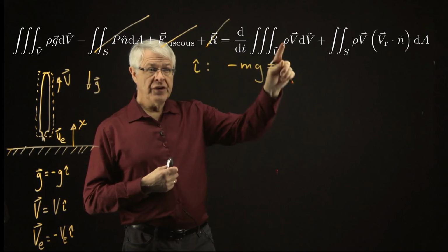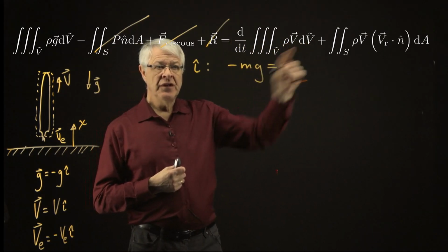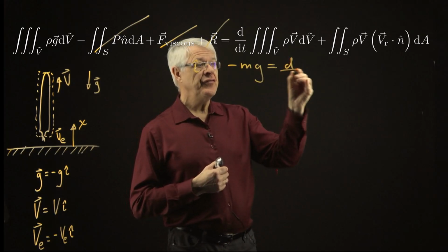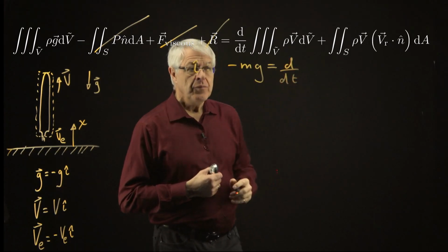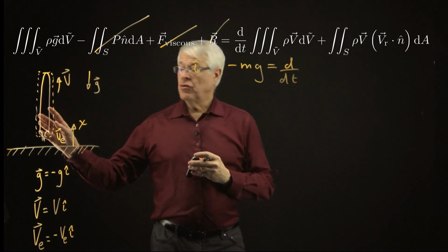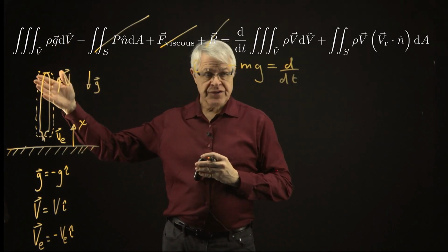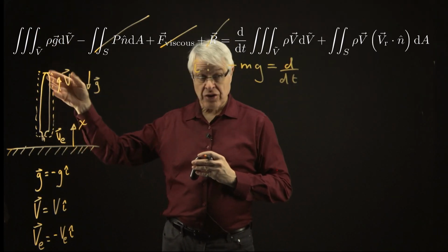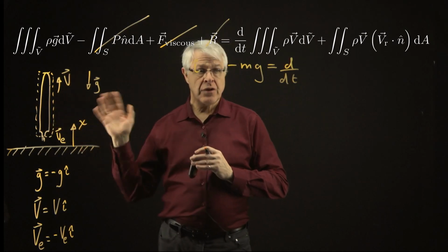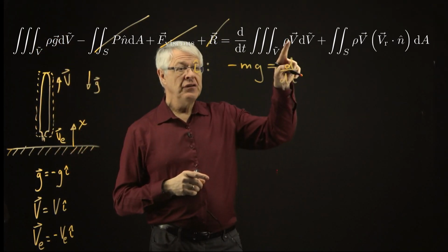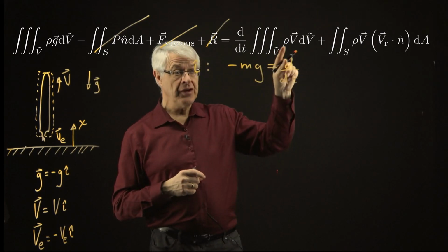So now we go over to the unsteady term, the rate of change of momentum. So we need to keep that derivative for sure. But everything in this control volume is moving with the same velocity. So the rocket housing, the unburned fuel inside, the parachute if it's in there, fins on the rocket, all of those things, they're all traveling up at the same velocity. It's not constant.